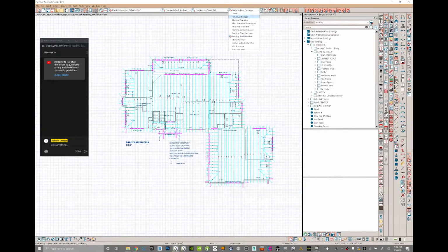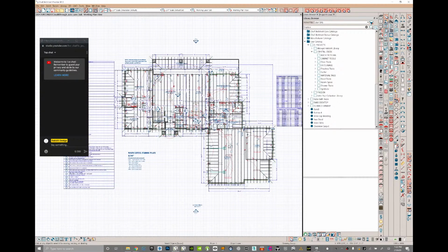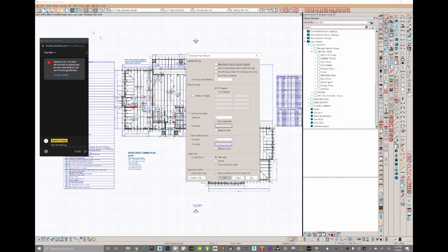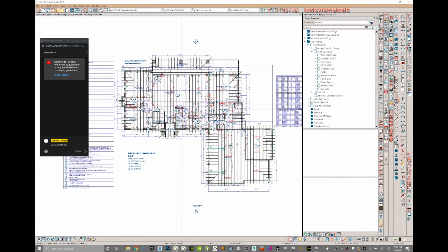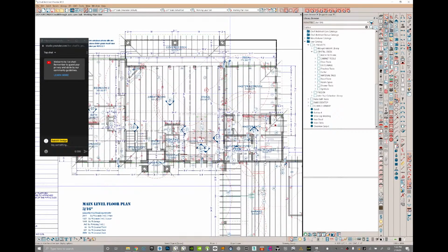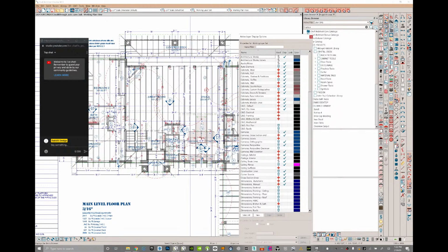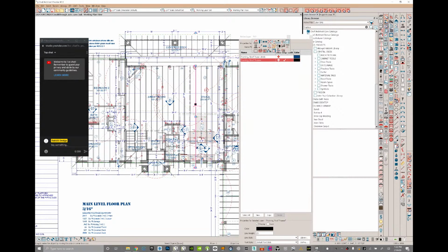So this is the first time I'm looking at this particular project. Let's just get to a better working plan view. This is someone else's template, so I like to clean up these templates just for myself so that I can see a little bit better. I'm going to turn off these snap grids, turn off the regular grid, and start making some of these elements just disappear in my working view by opening up active layer display options, nicknamed Aldo.